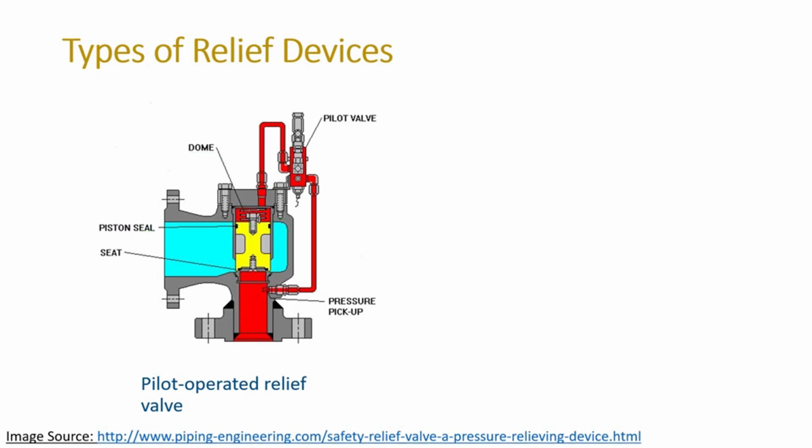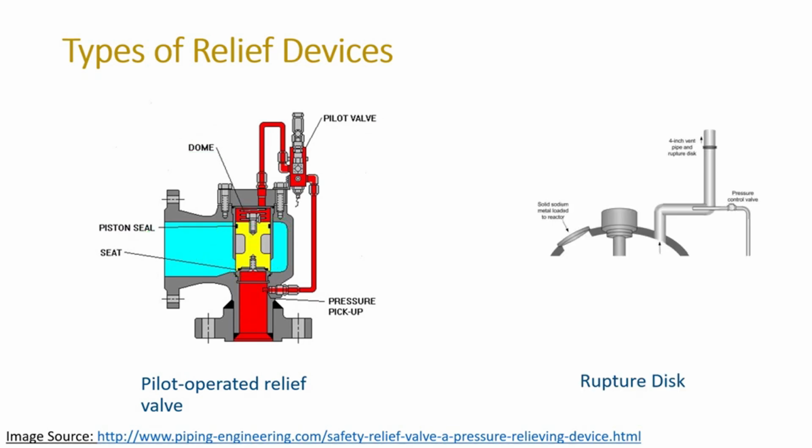The last type of relief device that we're going to look at are rupture discs. Rupture discs we saw earlier in the course in the context of the T2 Laboratories incident. And a rupture disc is a thin diaphragm, usually a solid metal disc, that's designed to rupture at a designated pressure. So in the T2 Labs incident, we saw that the disc ruptured, venting hydrogen to the atmosphere.